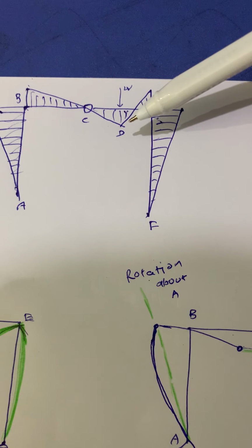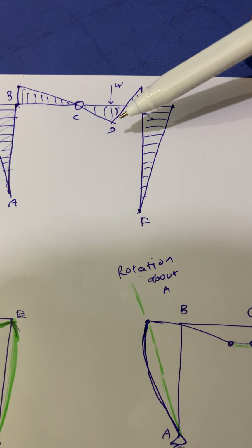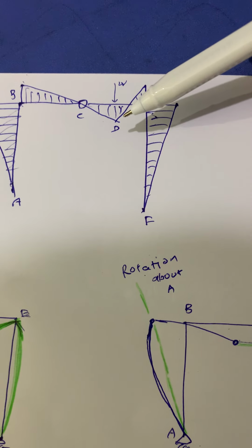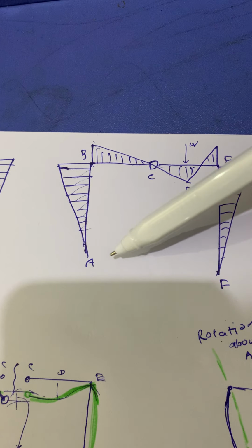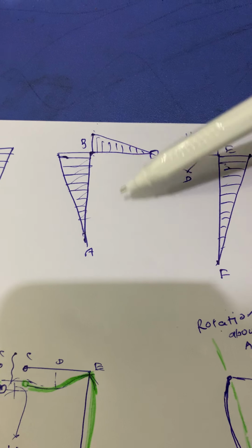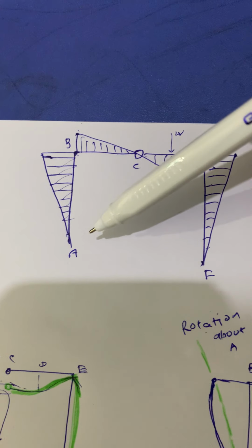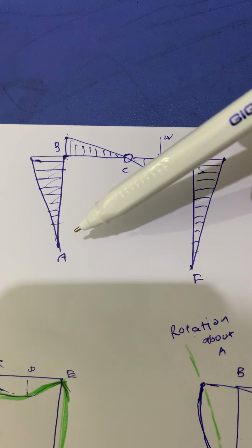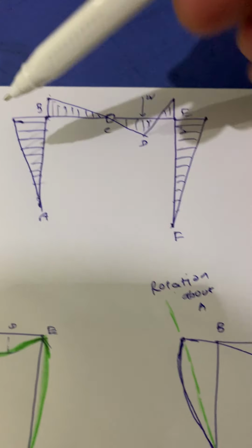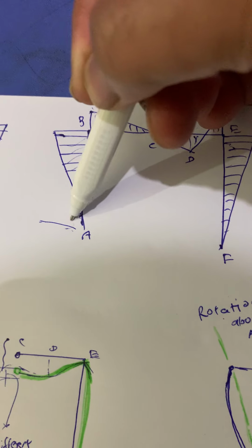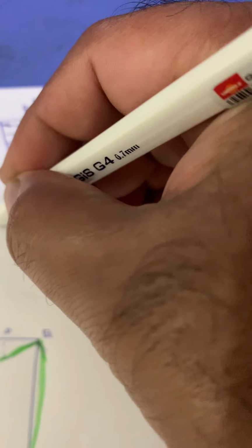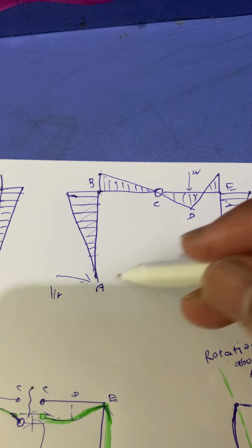We saw a similar effect when we studied the case of a beam with internal hinge. You will note that this effect is consistent with our known values of the support reactions. The bending moment at B is clockwise to resist the anti-clockwise moment caused by horizontal support reaction at A. Because of this horizontal support HA, it is causing the anti-clockwise moment.